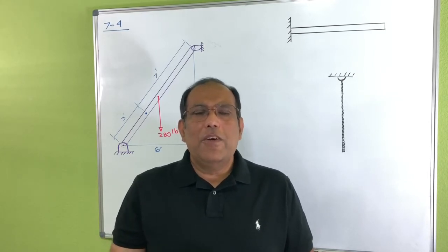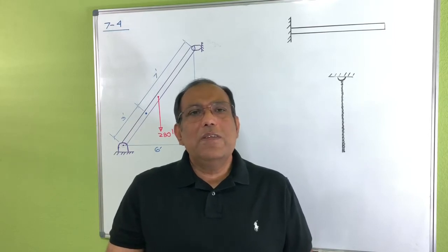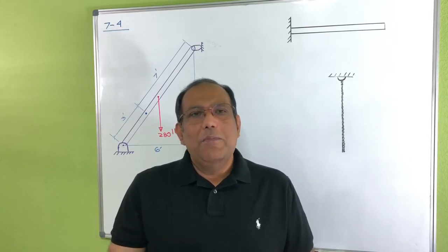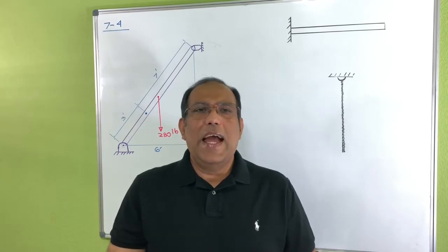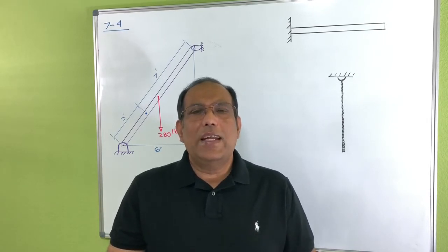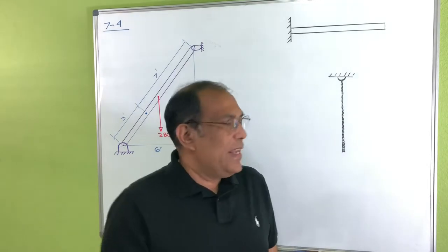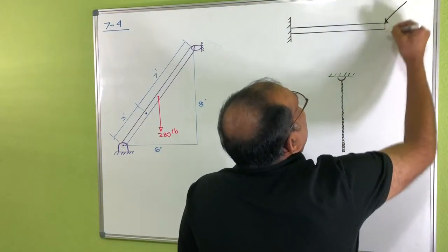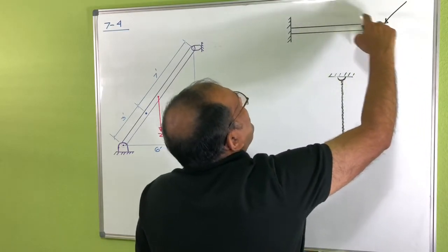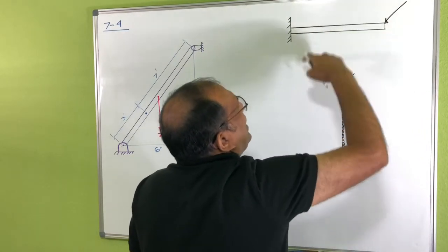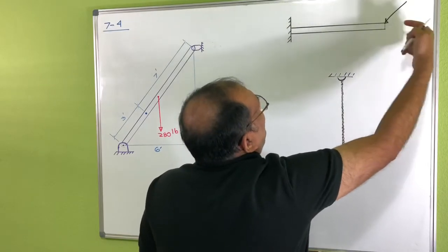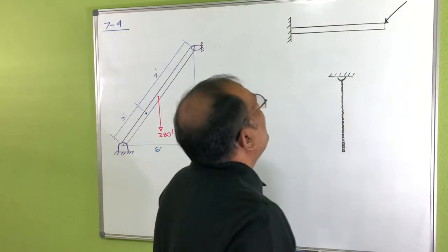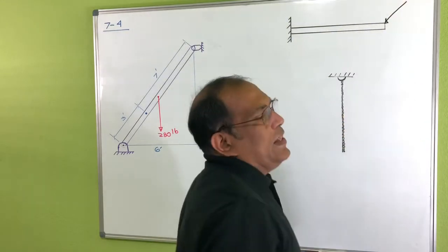Okay, for engineers, it's our duty to design the material based on different thickness and size so that it can take the required force for that particular member, right? Let's say here, for a beam, if I apply load here, then you see this beam will try to rotate like this. There will be a compression force in that direction and a shear force in that direction.